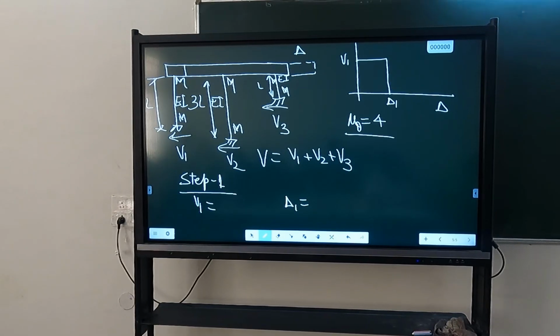I have given same. What's the problem if I give same? Why? I am making a bridge in which all the 3 pier sizes I have kept same. I have only varied height. Stiffness will not be same, EI will be same. So I have not said stiffness is same. I have said EI is same.